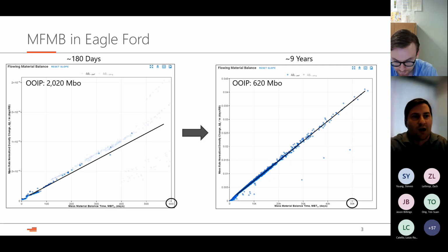It is completely closing off those fracture tips and getting shorter and shorter fracture half lengths. Okay, thank you. Absolutely, that is a great question, and it's just like some of the cases that Mo showed as well with fairly significant pressure dependent perm here. You would see it bend eventually. It would just take a little bit longer time. But as Steven says here, this is basically the same line, and it's been on that line for 9-10 years, which is almost 3,000 days or so.